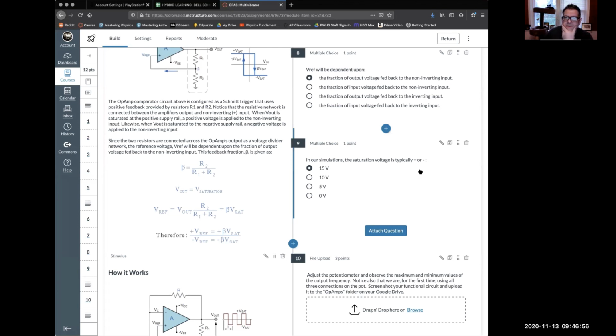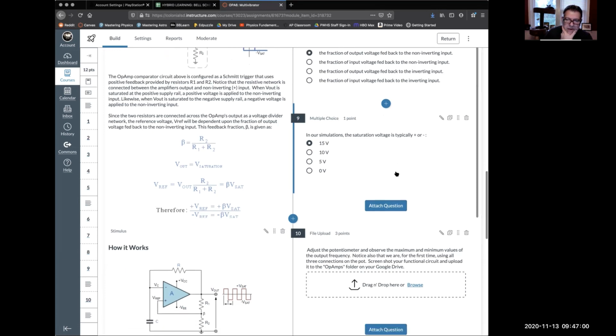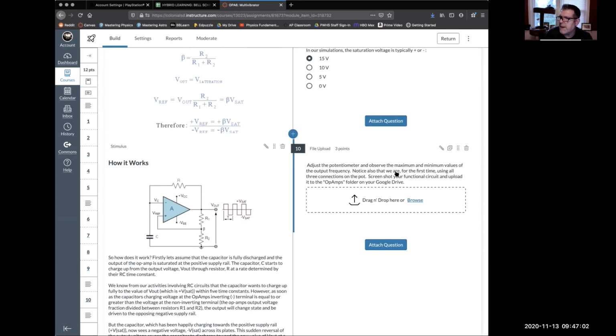In our simulations, it calls for plus or minus 15 volts. Oh, and we did an op-amp thing where I suggested, when you do that simulation, that you just set it to plus 100 and minus 100 volts. That's not realistic, because that will blow an op-amp up. The op-amp just bursts into flames. But it made the simulation work properly. It meant that voltage was not an issue. The op-amp could operate at any voltage.